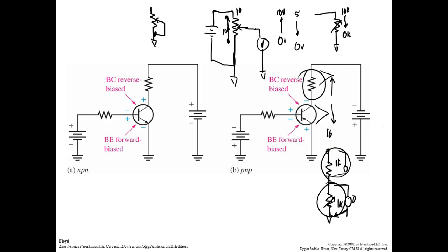Now what's causing the voltage drop across that to go up? Because the resistance of the transistor is going down, the current flow in the circuit is going up, which is causing that top resistor to drop more voltage, right? But we're doing that by controlling the current. And that's why a transistor is a current valve. In electronics, it's the equivalent of a rheostat, but a rheostat's got a knob on it. A transistor doesn't have a knob, because we're controlling the resistance of that transistor with a base current. And we can control it precisely.